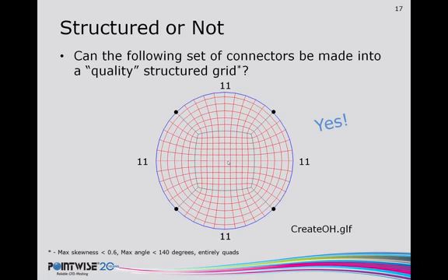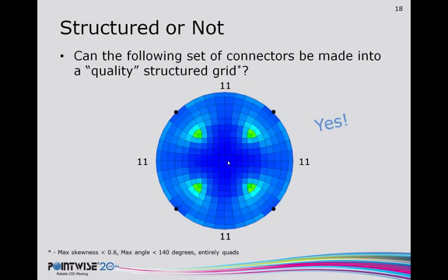So these grids can produce very good quality cells throughout. You have excellent orthogonality near the edges, which is great for boundary layer resolved flows. If you wanted to, you could go back in here and very easily apply a viscous spacing here. And so this topology is very, very good for these circular or rounded geometries.